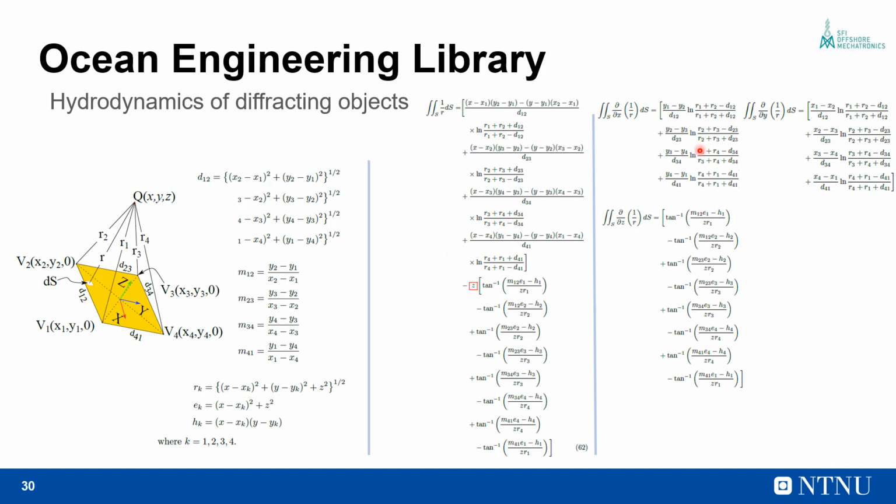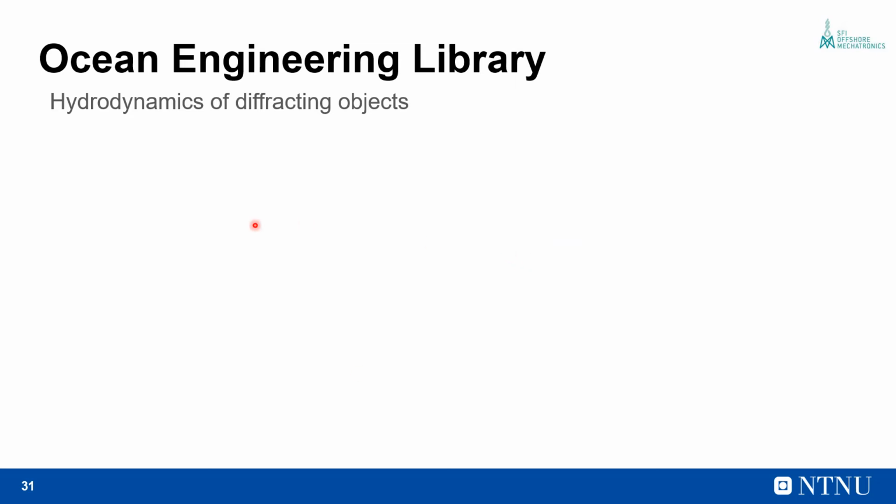From the analytical expressions for the directional derivatives, we note that the x and y directional derivatives go to infinity at the panel edges, and the normal directional derivative is singular at the centroid point. In our code, we avoid this singularity by assuming that the source panels lie at a small distance beneath the body panels.